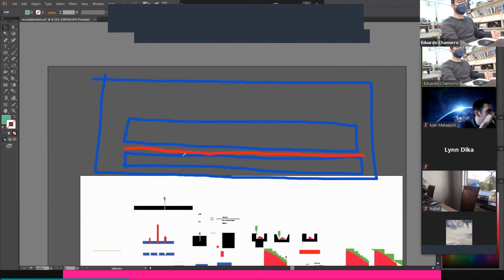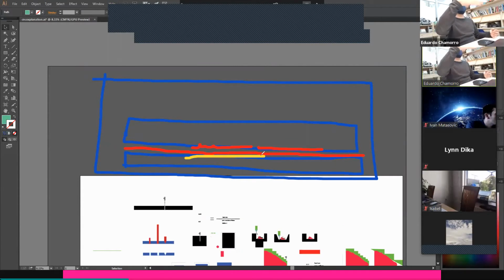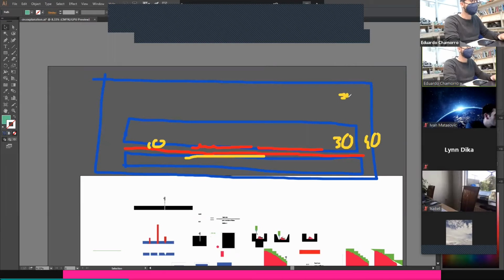When you're cutting the part next to it, when you have cut this one, this side is already loose, and then you cut this side, so the piece of wood is not attached to anything, and it vibrates a lot. In this case, you don't want to use, for example, 10 millimeters here. You want to use like 30 or 40. It depends also on the geometry you're cutting. If it's a full plank, I will leave 30, 40 easily. If it's a really small area, maybe we can reduce this margin to 5. We can make them thinner, so we save a little bit of material.